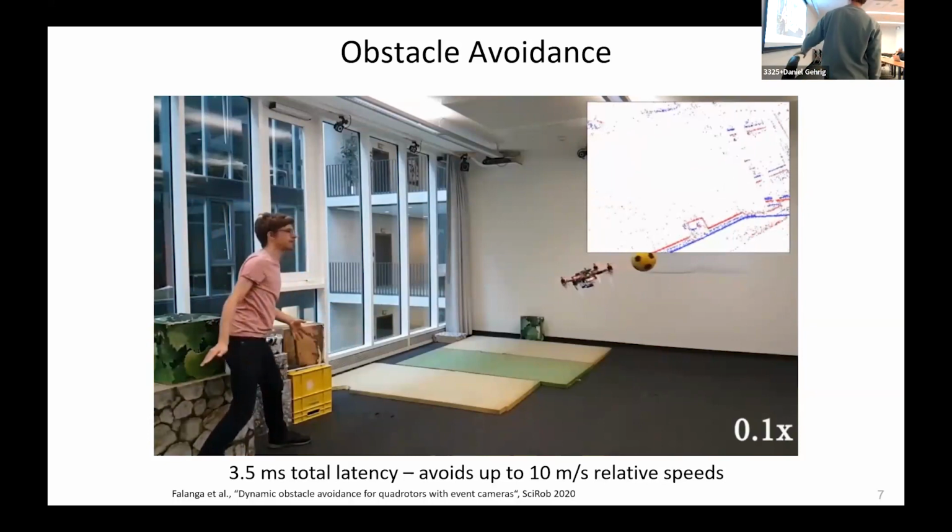And this is mostly possible because the event camera has such a low perception latency. You can imagine that achieving this kind of latency with a frame-based sensor would require a very high frame rate camera, which isn't feasible in this case. This actually allows us then to avoid obstacles at up to 10 meters per second speed.